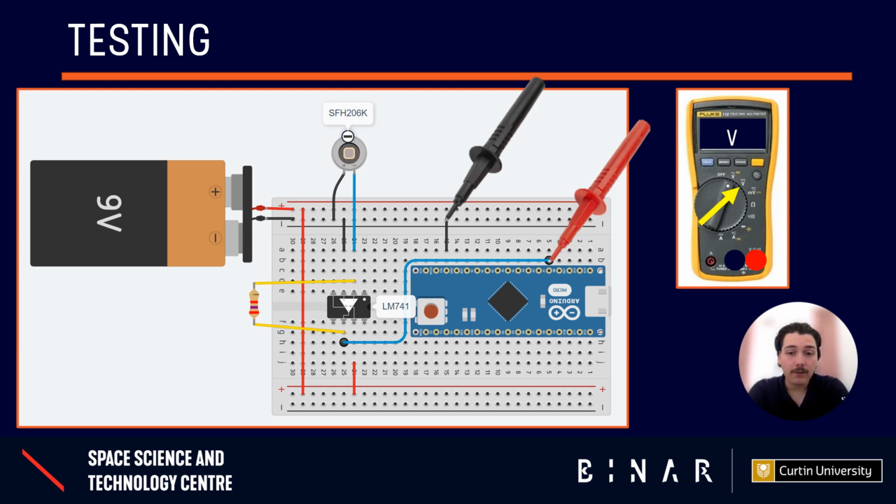If your photodiode is facing the wrong way, you're actually measuring the dark current, which I won't get into now, but it's not the current we're trying to measure. Then also check to make sure that your photodiode's lead heading into the op-amp is heading into the inverting terminal, the terminal with the minus side on the schematic. Then also double check that your feedback is coming from the output of your op-amp on pin 6 into the inverting terminal, which is pin 2.